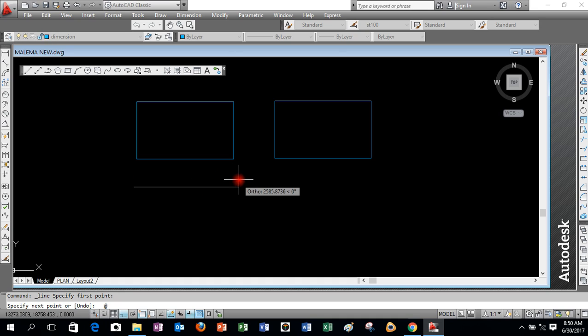Because it's going to be a relative rectangular coordinate method, my length is going to be 2,400. So I'm going to move 2,400 from the starting point horizontally, but not vertically. So it's supposed to be at 2,400 comma 0. If we were to move up by some units, then it wouldn't have been comma 0 here. So comma 0, then we press enter. So the line ends there.